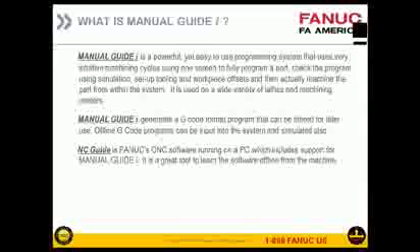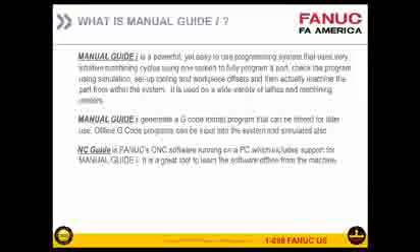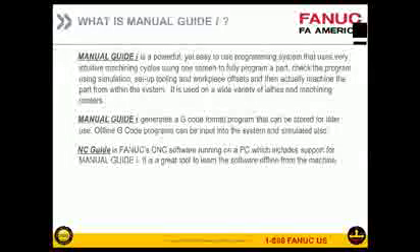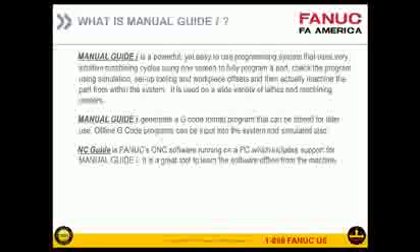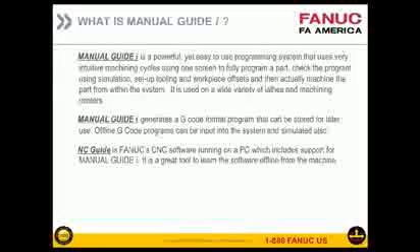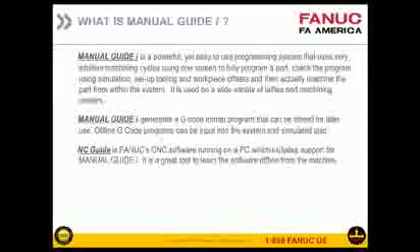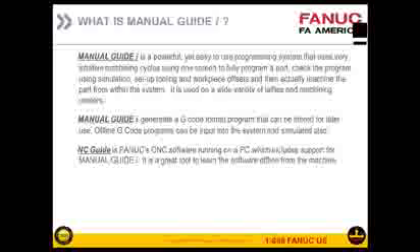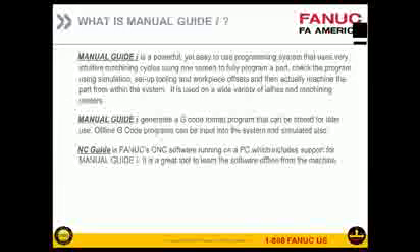Well, what Manual Guide I is, it's a powerful onboard conversational programming system that is available that uses intuitive machining cycles, both turning and milling, that you use one screen to fully program a part. You can check the part using simulation, set up your tooling, your workpiece offsets, and then actually machine the part